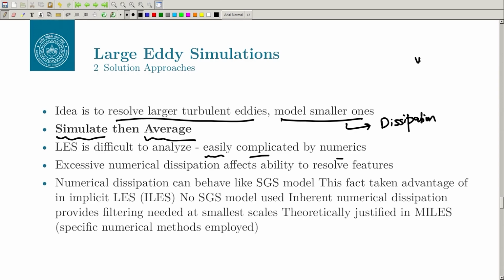Here you will get the quantities u prime, v prime, w prime, and so on, and if you want to calculate the turbulence kinetic energy, then you will have to calculate it from u prime bar plus v prime bar plus w prime bar, and so on. It requires a little bit of involved calculation, which I will discuss, how to calculate in LES also.